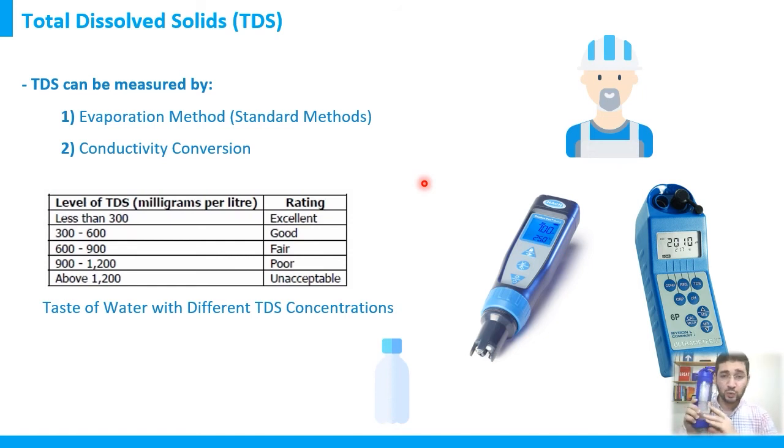If we take 1 liter of your water sample, we need to evaporate that water sample and measure the remaining salts by weight. So we calculate how many milligrams of salts remain in your 1 liter sample, for example a few hundred, or 50 milligrams per liter, or 1000 milligrams per liter. This is the only approved method internationally according to the Standard Methods for Water and Wastewater handbook.